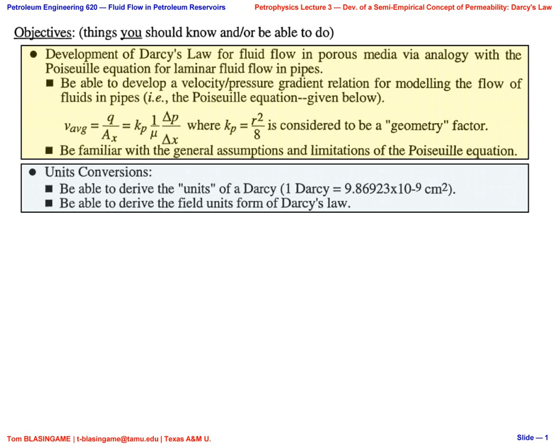So we're going to derive the Hagen-Poiseuille law. Now, for those of you who are not petroleum engineers or who may have some other issue with petroleum engineering, let me explain. We are not suggesting that you can use the Hagen-Poiseuille law to represent Darcy's law. We're suggesting that there's an equivalent capillary, an equivalent tube, that you can use to represent permeability. But what I wanted to do with this lecture is demonstrate the derivation of the Hagen-Poiseuille law, because we're going to apply the same concept as Hagen-Poiseuille law for Darcy's law.